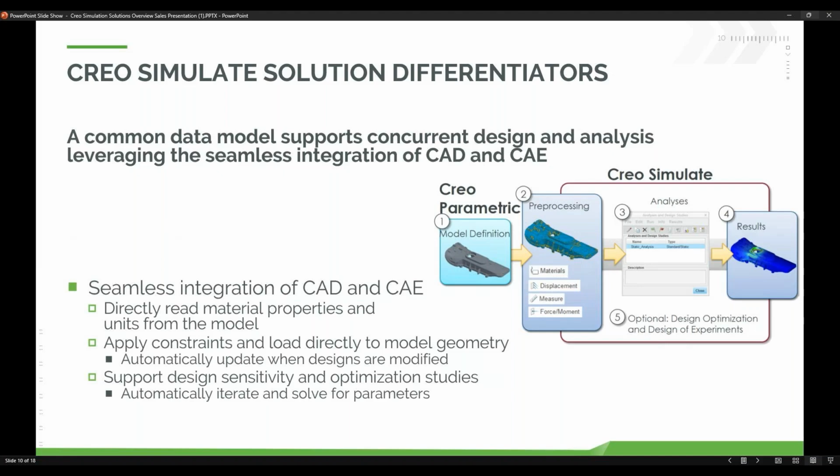We don't have to go back and remodel that geometry. We can actually go into the design study and change the value of that particular parameter. It will then reanalyze that model based on those new numbers. It does not update your model, but the design values will reflect the new numbers. And then if those numbers are valid, you could then go in and change your model.